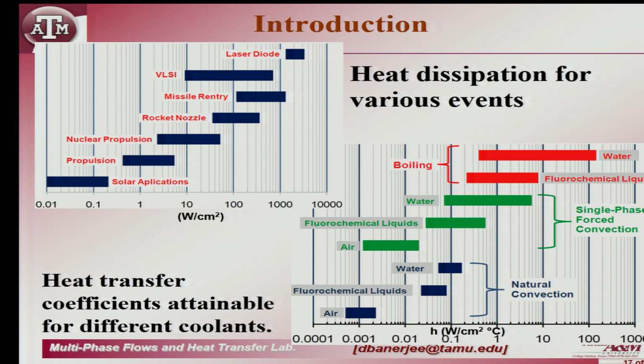So I have to enhance the performance. Boiling looks like the only option for that kind of cooling application, doesn't it? And so I need to somehow enhance the performance of boiling. That is the basic problem. I need to extend my boiling critical heat flux from the current technology of 100 watts per centimeter square to kilowatts per centimeter square. That justifies boiling research.